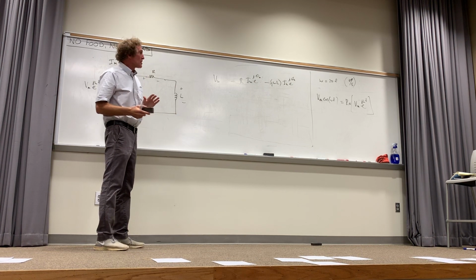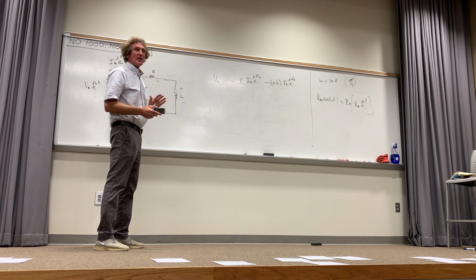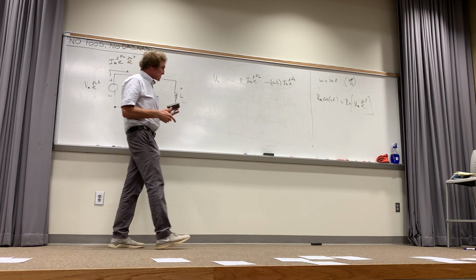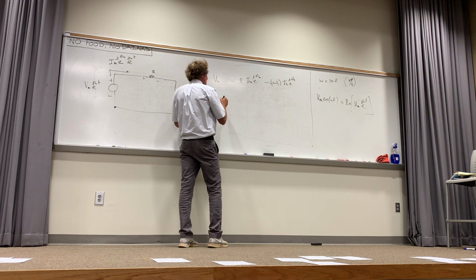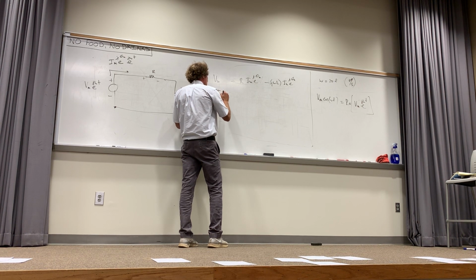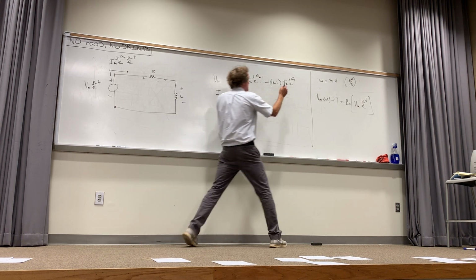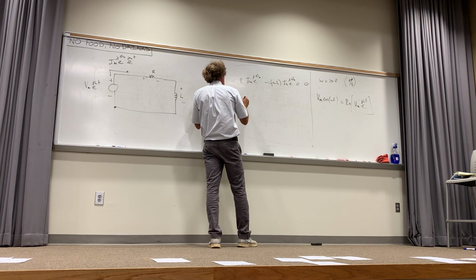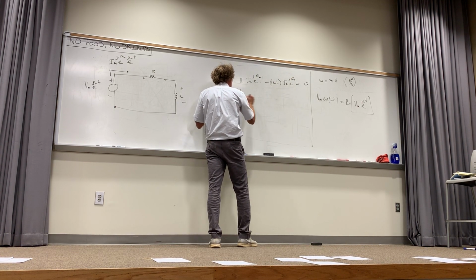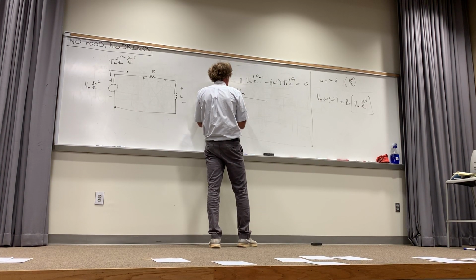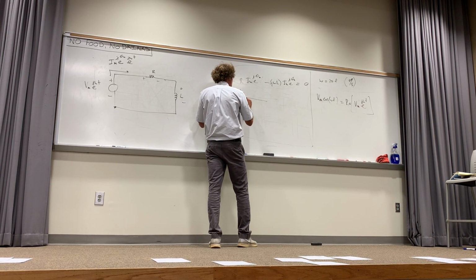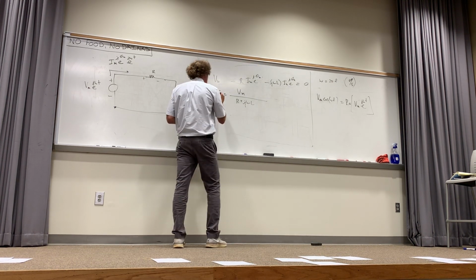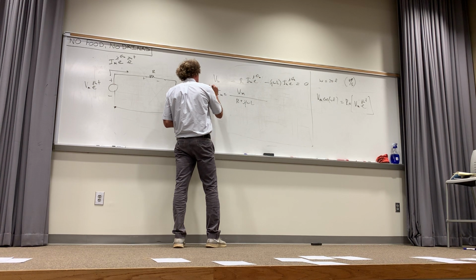Now, when I look at that, if I wanted Im, and the phase angle, just take a look at this. If I wanted the current, I could say the current Im was just equal to, this is all equal to 0, by the way, I didn't put that in there. It would be equal to Vm divided by simply R plus j omega L. And that would be this number, magnitude e to the j, the phase of that.